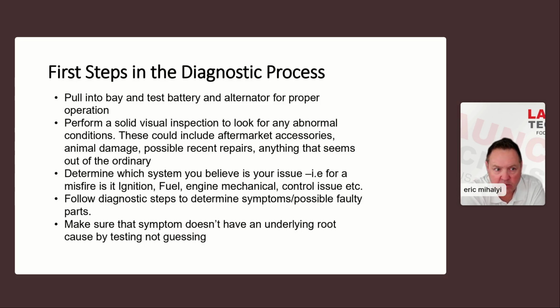But I've seen it where people have been chasing their tail, trying to figure out why a display on the radio doesn't work or the nav doesn't work. And I always say, did you ever bother checking the battery? No. So battery state of health is really important.